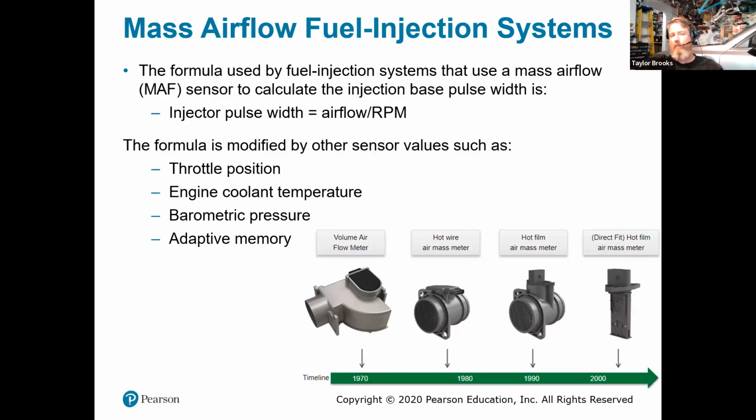So one of the things that we messed with was taking apart the mass airflow trap door and permanently keeping it wide open. The thought process was if we always tell the engine that it has maximum airflow, it will provide more fuel, a little bit richer fuel mixture, which then we can ultimately make a little bit more power. Thankfully, the person that made this mistake was the owner of the shop, because we very much feared him, and we probably would have felt we were going to lose our jobs and our lives at that point. But we were running the car on the dyno after he'd made this modification.